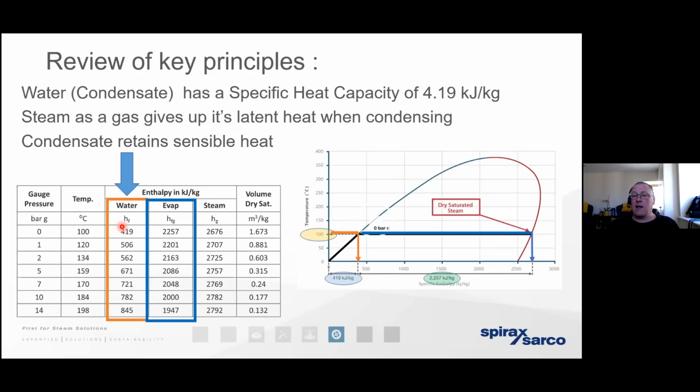And if we don't do that, then that standing condensate is likely to cause erosion, corrosion and rusting of the pipework and other components. And if we're distributing the steam at a fast velocity, it means we're highly likely to get erosion as the steam is conveying the entrained moisture across sensitive areas such as control valves and flow meters. And if those control valves start to erode, then it means that we're getting a very, very inaccurate and unreliable release of energy onto the process. But it also means we've got a solution that will need maintaining periodically.